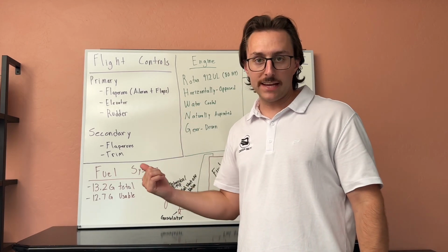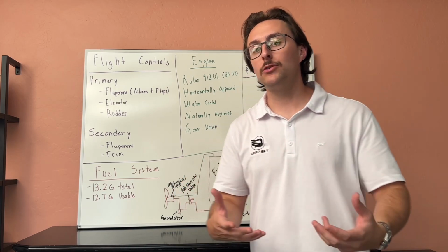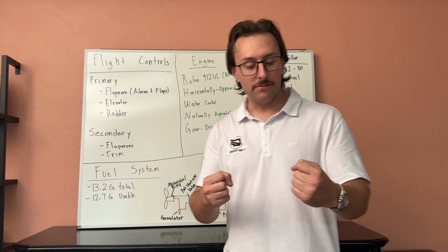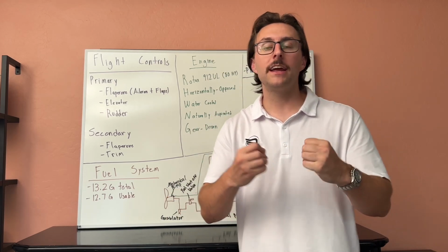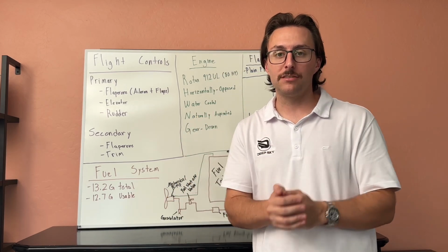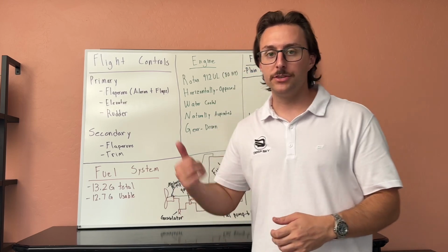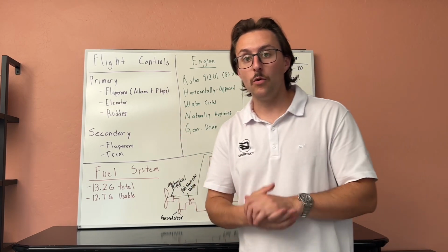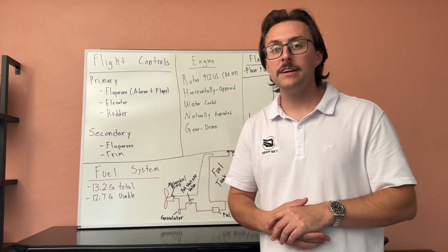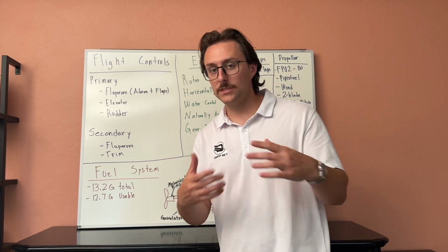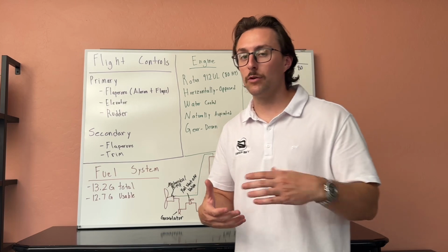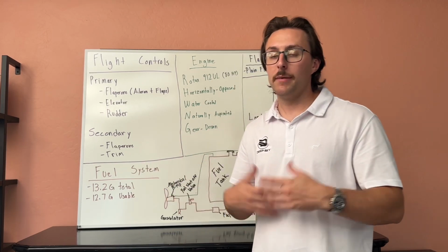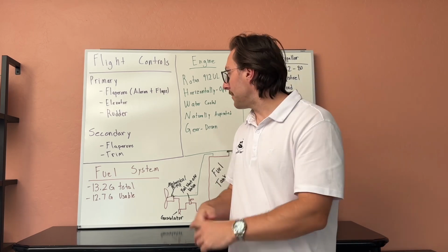It is naturally aspirated as opposed to, say, turbocharging, which is a forced air induction system that compresses the air so that you're getting more power out of each explosion when it comes to piston movement. Another time we'll have to go into the 4 strokes of our engine, but for today, all you need to know is that it's naturally aspirated, which means that there's no forced air induction. It just sucks in the natural air pressure from outside and then creates an explosion from that.